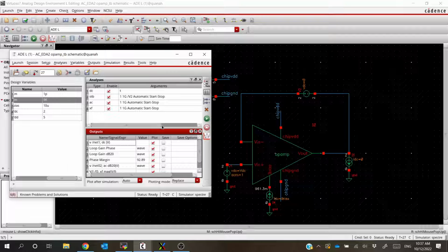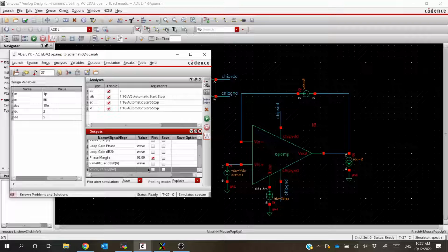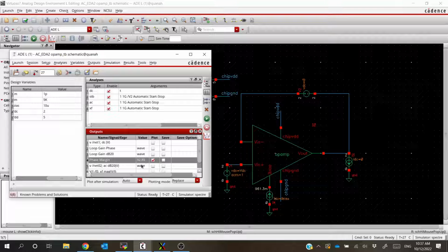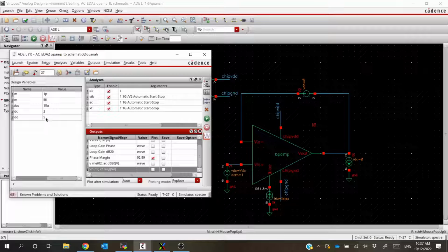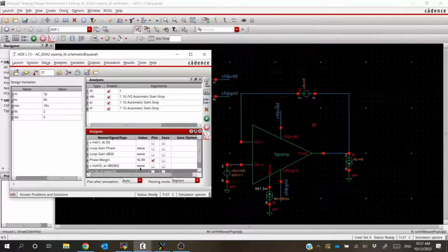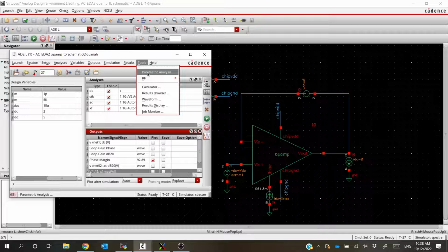Okay, so true to form, I did forget something that I needed to show you guys. Phase margin, the reason that we want it to be so high is because the circuits that we make aren't always going to be operating under ideal conditions. For example, a change in VDD can definitely impact our phase margin, and a change in the ambient temperature can also have a pretty bad impact. So we want to design with enough headroom for some non-idealities without completely breaking our circuit.